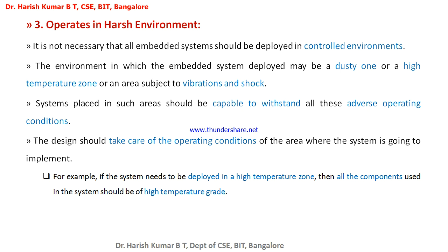The design should take care of the operating conditions and the area where the system is going to be implemented. So for example, if I want to develop an embedded system and deploy it in a high temperature zone, then all the components which I am using to make that embedded system should be high temperature grade. Because I don't want my embedded system components to get melted because of the high temperature zone.